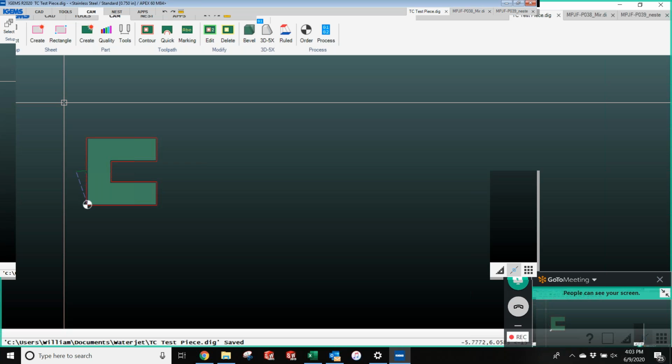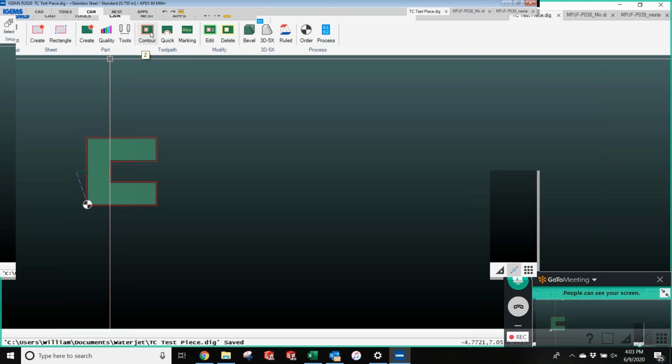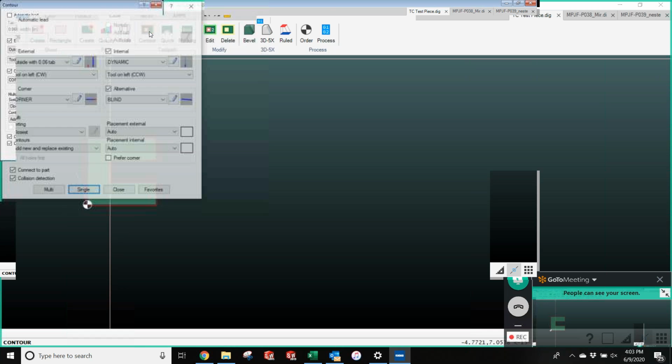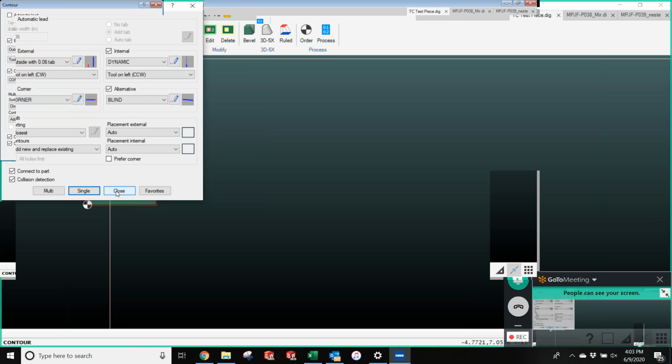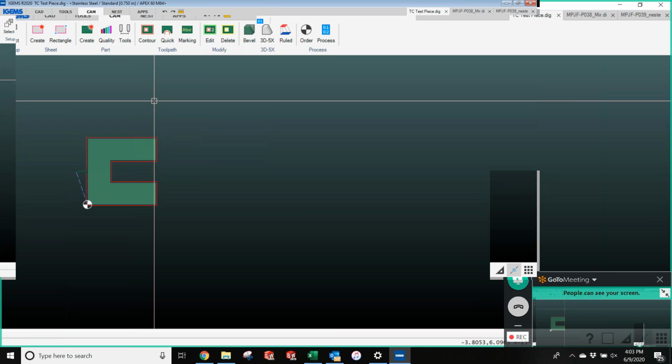So for a lead-in for a hole, everything I've always seen in plasma, oxyfuel, and others, the lead-in is always more of a radius lead-in instead of a straight in and then start turning in the hole. Is that just different on the water jet? It's not necessary? Does it help anything? We usually find that on metal, a straight line lead-in tends to work out a little bit better because it kind of forces the jet to slow down when it comes to that sharp corner.